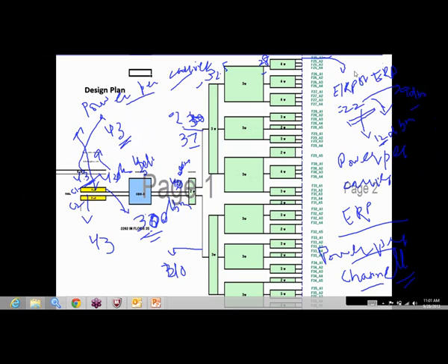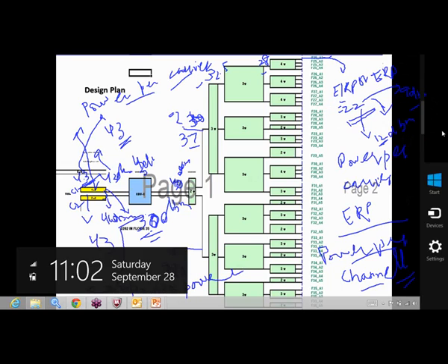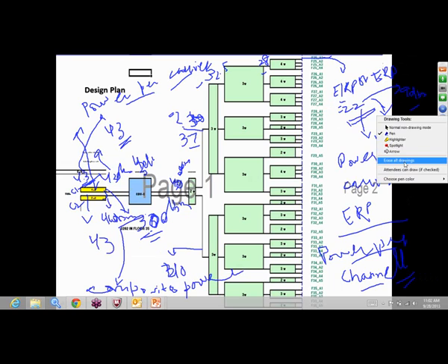Okay, composite power is not so much different or difficult. What composite power is, this is 43 dBm for carrier 1 or 43 dBm for carrier 2. What composite power does is add these two powers and say this is 46 dBm. Okay, 46 dBm, and this is called composite power. So whatever your EIRP calculation for power per channel was, you will add 3 dB, so you will get composite power. You will subtract about 10 dB, whatever your difference between total power and CPICH power, you will get ERP for CPICH power. Okay, so it's simple. You do the calculation on the basis of one, and you add or subtract, and you get the other results. So it's not so complicated. Okay, guys.